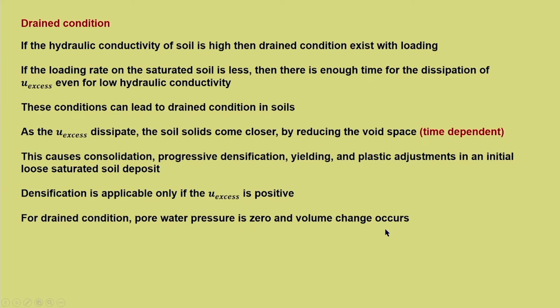So, now this is another important fact which we need to keep in mind. When the condition is assumed to be drained, we understand that there is no pore pressure development and volume change happens. When we know it is undrained, pore pressure develops, and volume change is 0. So, these are the two important aspects which we need to keep in mind, and this influences the soil behavior.